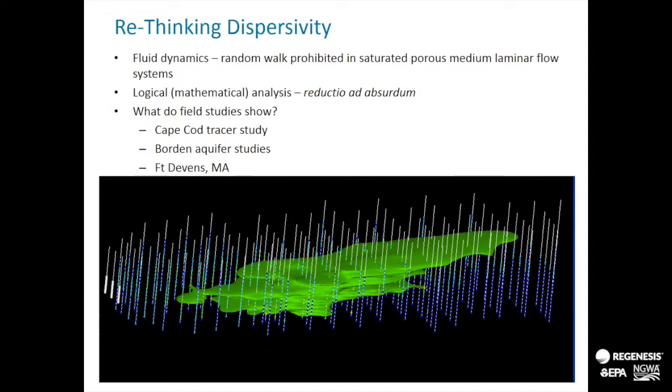vertical profile. And so if you're sitting at the end of this with a long well, you start seeing tracer arrive at this point, and the last of it goes through when this part of the plume goes through, and you say this is a longitudinally highly dispersive aquifer. Well, I suppose, but it would be more useful to think about it as a family of velocities, each of them relatively low dispersivity, but when you look at it in a longer screen, you're going to perceive it as a highly dispersive situation. So going into the more highly resolved pictures of our sites allows us to also abandon the notion of longitudinal dispersivity and substitute it as heterogeneous advection.